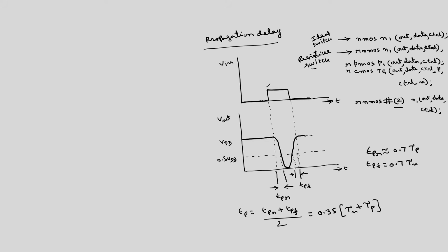If you have only one value, then it represents the propagation delay. On the other hand, if you have something like rpmos with 2 values, say #(3,4) P1 (out, data, control), these 2 values represent the first one as rise time and the second one as fall time.